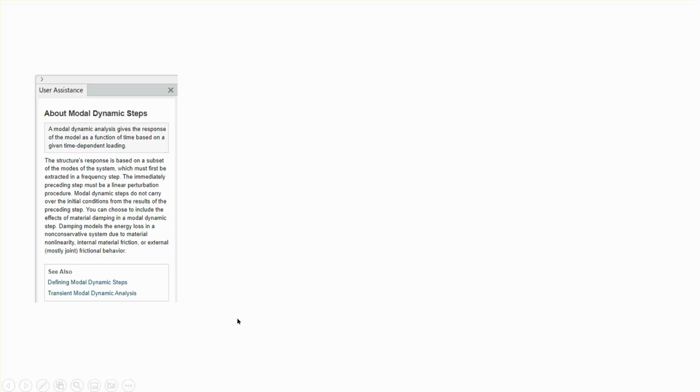And that's exactly, incidentally, what I did in the implicit dynamics video tutorial. I first started with a static procedure, stretched the spring by some amount, and then in the second step, which was actually implicit dynamics, I deleted that initial displacement that appeared in the previous step.